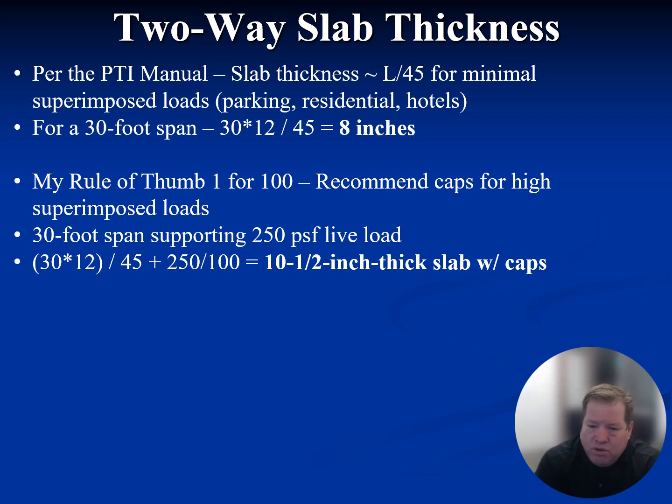Punching is an issue. Obviously, caps, stud rails, you can use them. The caps will have an effect on the slab thickness. So if you get rid of them and use stud rails, reevaluate the slab. They are not interchangeable just like that.